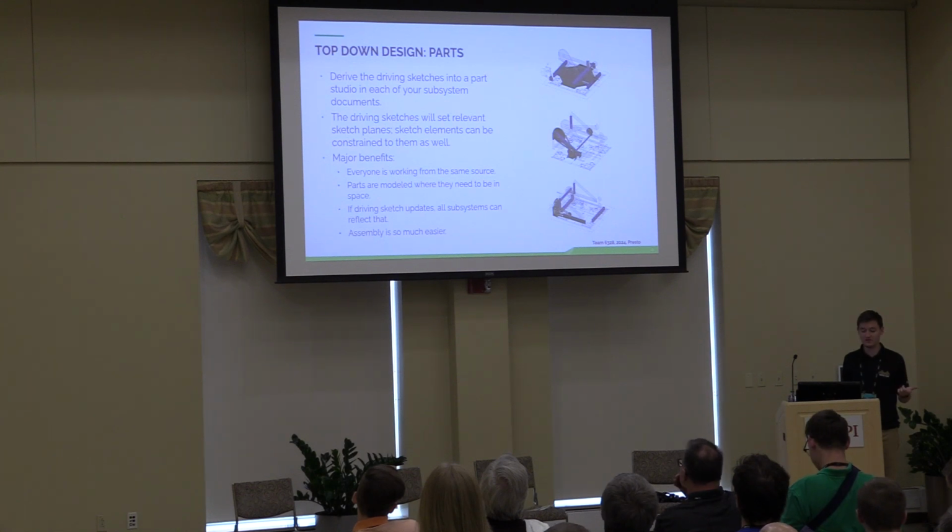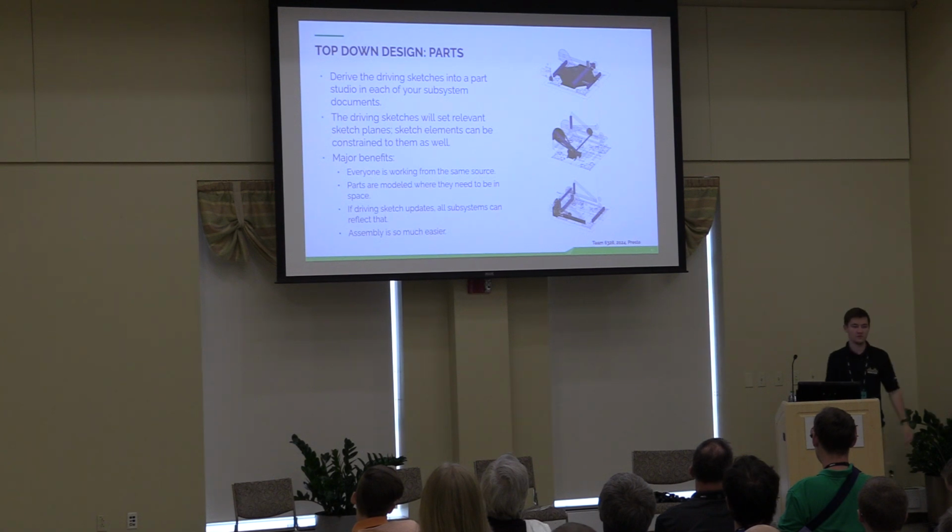If the driving stage updates and you've done proper parametric practices, you can actually have some flexible parts so that things will update if you need to stretch the drivetrain, compress the drivetrain, or you're trying to make your pivot point move up or down. You can do that by changing the sketch, which then will cascade down to the parts. It also makes assembly so much easier, which I will show in a little bit.